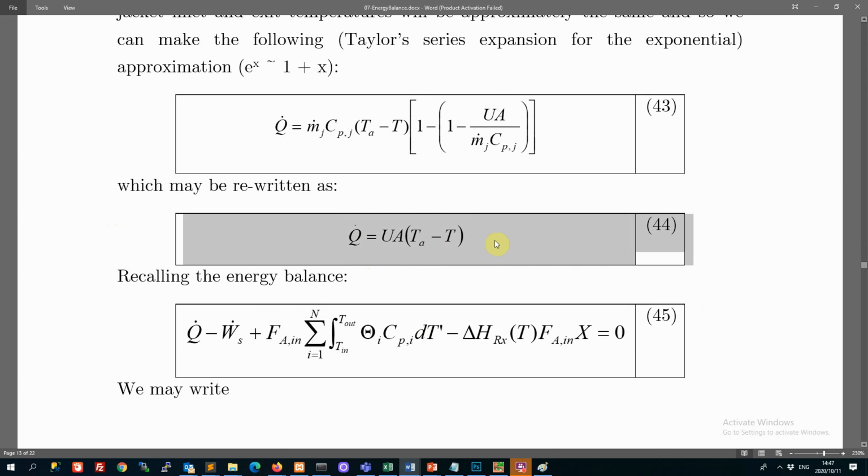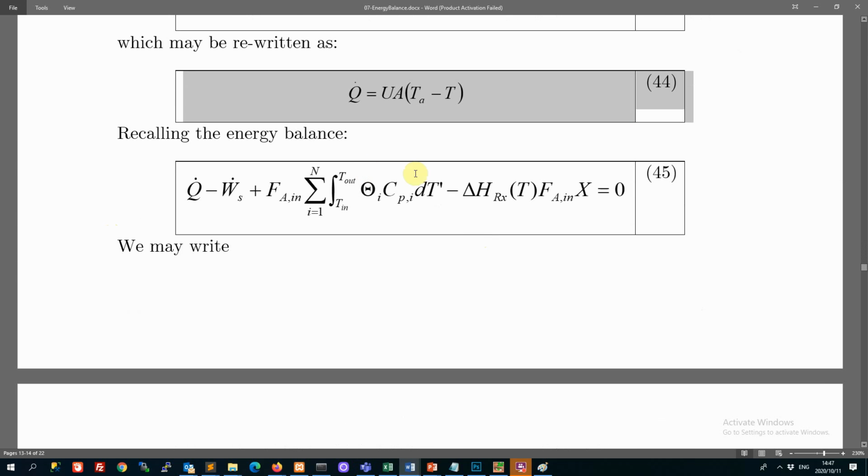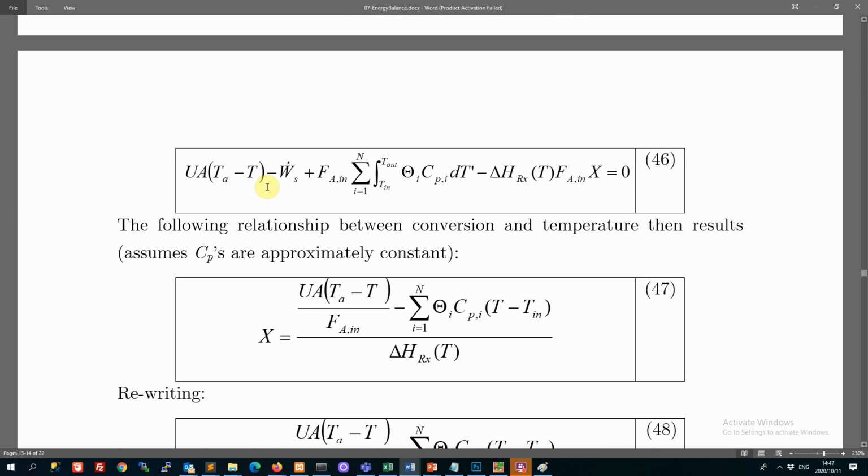And of course, there are some things. Your flow rate has to be high enough and all of that. But anyway, your Q dot term can likely be unpacked in this way. So as engineers, those are the nice simplifications we can make, and that's how we can progress the field. We also typically find that the shaft work is relatively small in comparison with the other terms. So we typically neglect this, even though we can just read it off the motor. So that's not difficult to do. But anyway, we can write a balance like this.